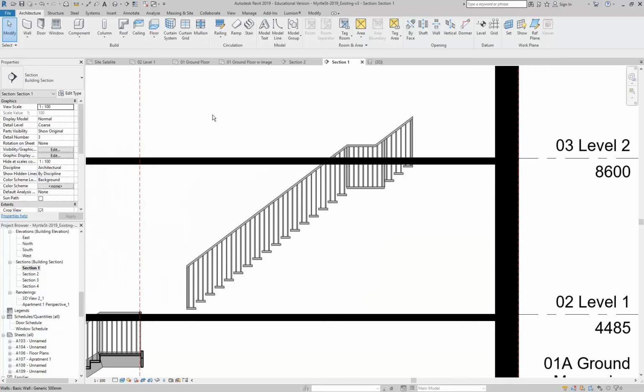But they've got an extra provision for stairs. You can actually go to 2 metres. Yeah, you can. I've been in court cases where we've done this, and it's a good thing. Because often where you've got little beams and things that come in over your stair, they do need to go fairly low. So, yeah, you can go to 2 metres, definitely. So that's just for stairs, only stairs let you go to 2 metres.